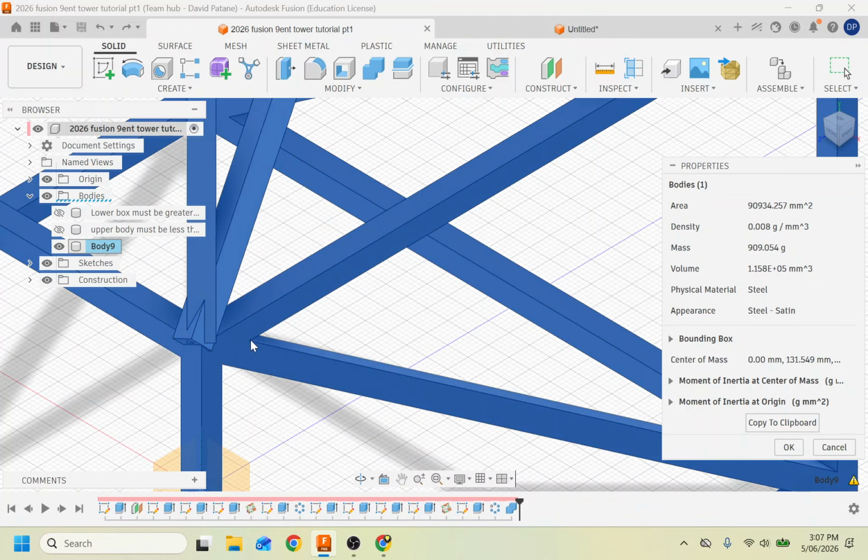I would say because some things you're going to need extra, for example, this one here in the corner, you're obviously going to have to cut your balsa wood at an angle to make that piece, right? But over here, it's assumed you did a perfect cut. That grammage you wasted there, you're using somewhere else. So maybe add like a 3 to 5% buffer to account for you cutting your materials together. But that's a good approximation. You can find out how much volume of balsa wood you have and you do this design.